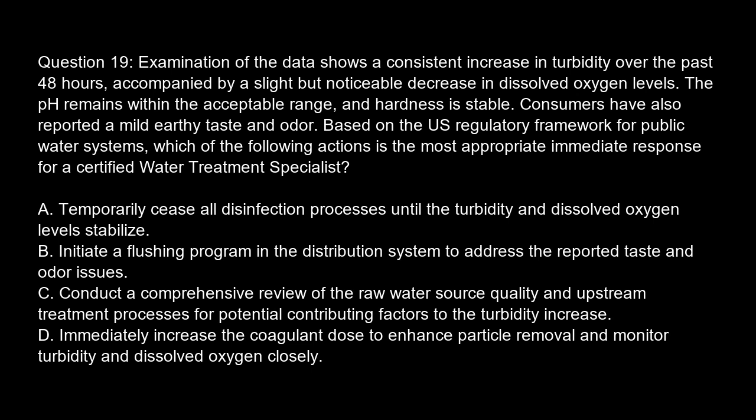Option A. Temporarily cease all disinfection processes until the turbidity and dissolved oxygen levels stabilize. Option B. Initiate a flushing program in the distribution system to address the reported taste and odor issues. Option C. Conduct a comprehensive review of the raw water source quality and upstream treatment processes for potential contributing factors to the turbidity increase. Option D. Immediately increase the coagulant dose to enhance particle removal and monitor turbidity and dissolved oxygen closely.